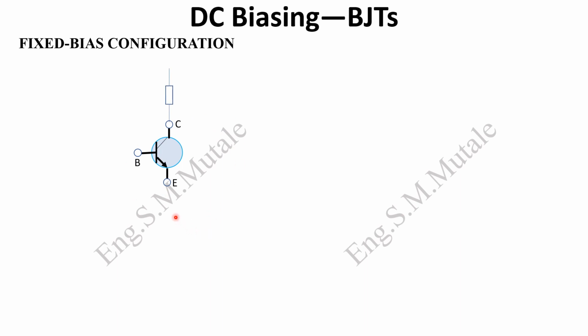You're going to connect a resistor on the collector, and you're going to call it RC, which is just the resistor connected to the collector. Then you excite it with some voltage. We are exciting the collector, which is why we are calling it VCC. VCC was just picked as a term to show excitation. There is a current passing through the collector resistor, and that current we are calling IC, or collector current.